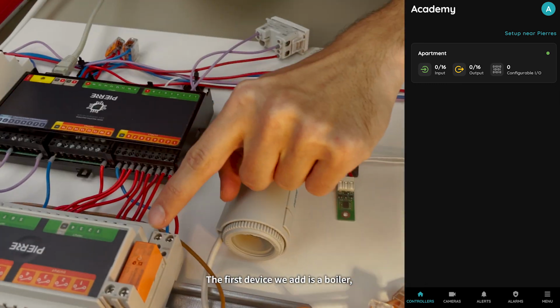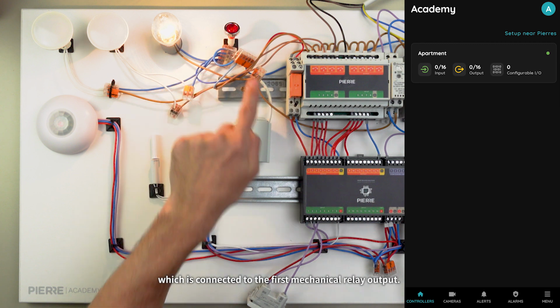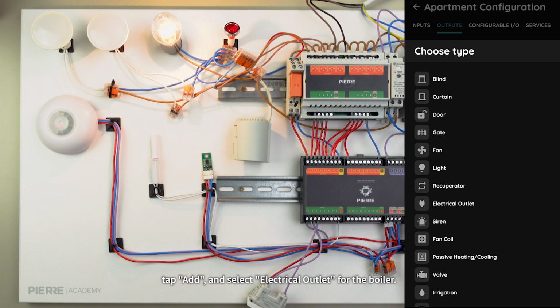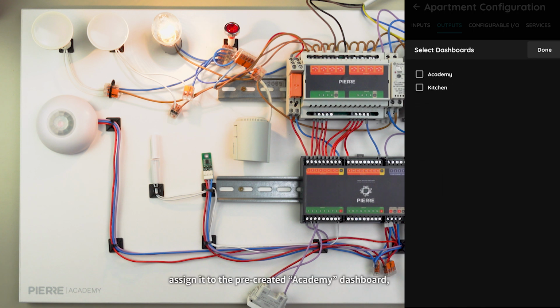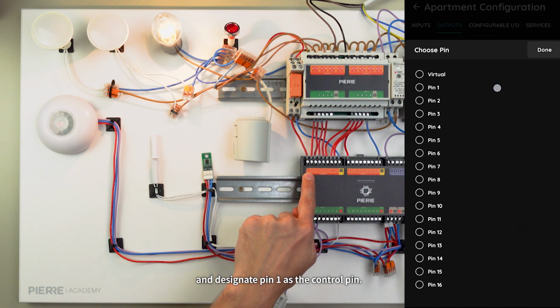The first device we add is a boiler, which is connected to the first mechanical relay output. In the app, we navigate to the Outputs section, tap Add, and select Electrical Outlet for the boiler. We name it Boiler, assign it to the pre-created Academy dashboard, and designate pin 1 as the control pin.